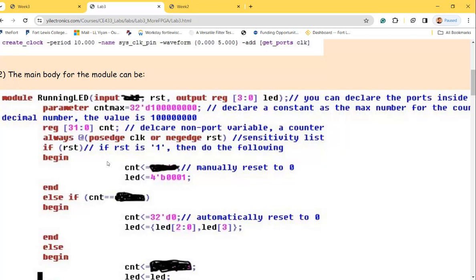There's a huge benefit of using that always statement with a positive edge triggering mechanism using a clock. You are thinking, why do we have to wait for the clock to do something? What's the reason for that? You can synchronize things. You can always keep things updated, and it doesn't matter because it's super fast. Nobody cares. You are thinking, wait, who is waiting? It's the fastest thing probably in the lab or in the building, so nobody cares. It's going to update things really quickly.